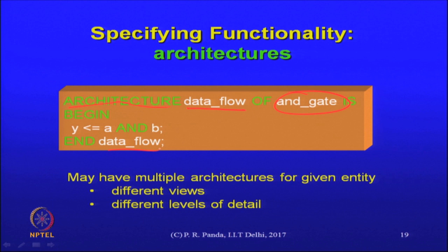Ultimately, when we take it up later for simulation or synthesis, we have to indicate which architecture, which implementation we would like to synthesize or we would like to simulate at this stage, but the language provides us the ability to specify different implementations. That would be by specification of different architectures.